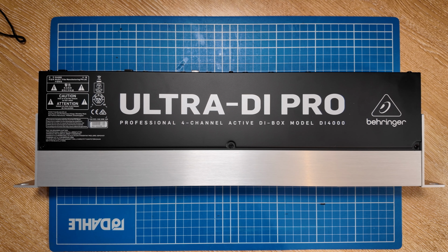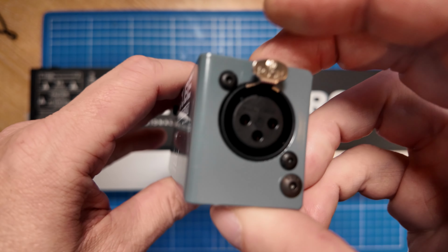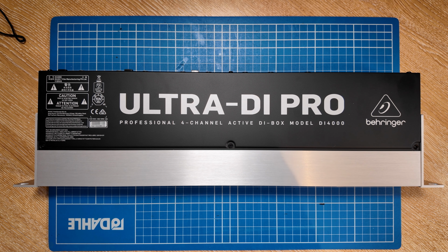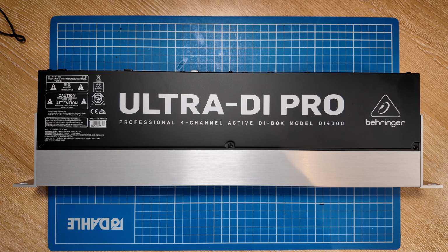Now, for the microphone connections, obviously the IC1 Ice Cube is absolutely perfect. But for some of the connections between the rigs and the mixer, where we want maybe the speaker output from the rig to go into the mixer and the output from the mixer to go back into the rig, we can't really use the line isolator because there's an impedance mismatch. So we're going to use something called a DI box instead.